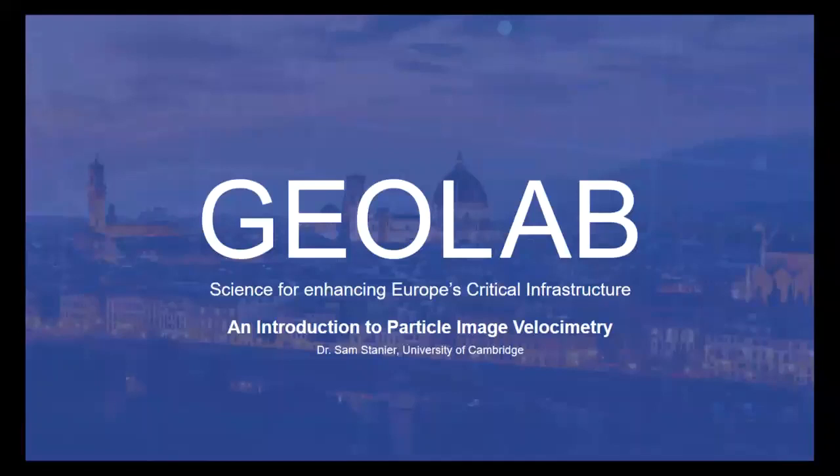I think there's some scope in that, but there's one big problem with those transparent soils, particularly the ones that are mimicking clays, and that is they're very, very light. They've got a very low effective unit weight. So even if you shove them in the centrifuge to try and get the stress similitude right, you've got an additional scaling factor there because the effective unit weight's about a fifth of what you'd like it to be. So ideally, you'd have to run the centrifuge even faster than you would for a real material.